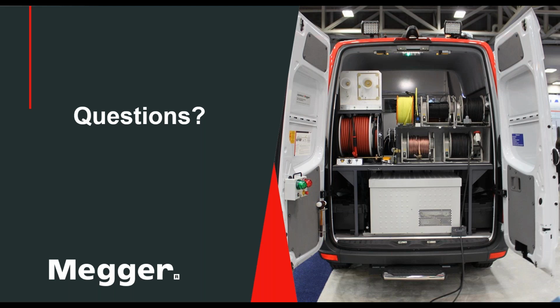If I have 50-50, then I can build an average velocity and use that. But always keep in mind, whenever you average or calculate velocities, the fault, depending where it is actually located, might have an impact on that distance.